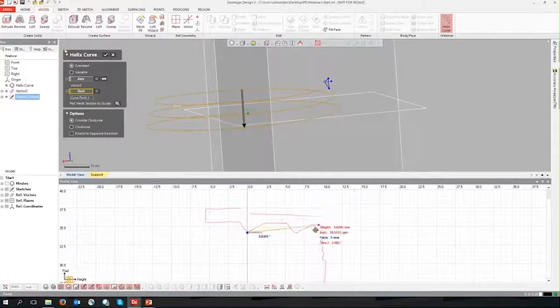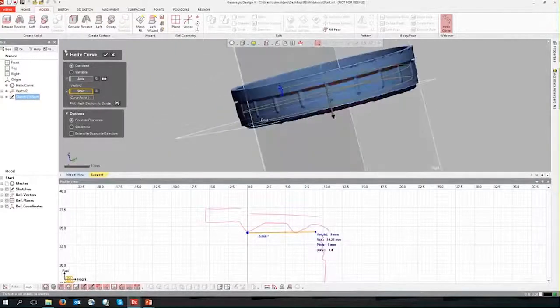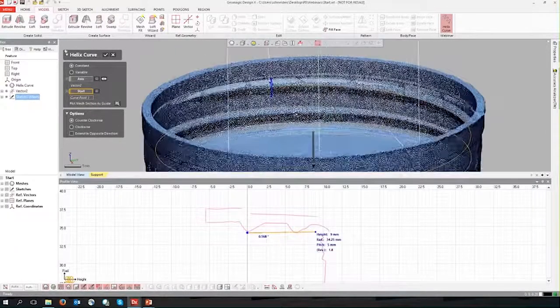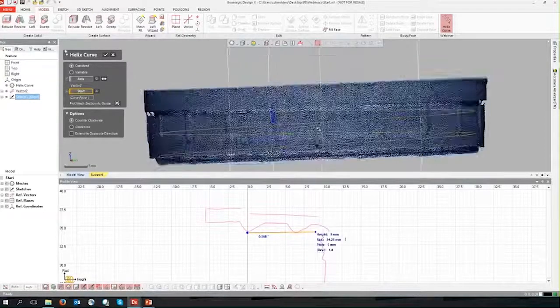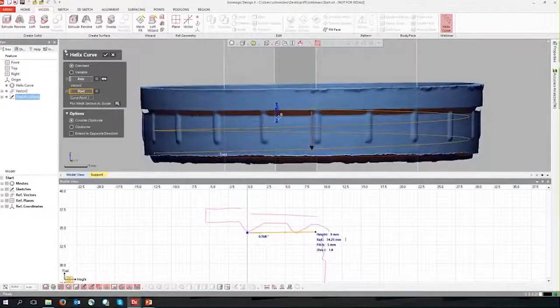This is where the 2D profile is nice, where if we do see a kind of funnel shape here, we can use the top of the teeth here as a guide, right? So turning our mesh back on. Looking nice. Here we have some other parameters that we talked about in our setup tab. We have our height, which is the top to bottom height of the helix. We have our radius, so this will be the radius at this point. We have the pitch, which is the top to bottom height of one time around, right?